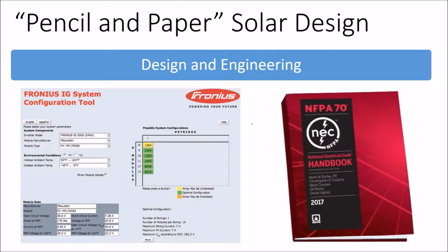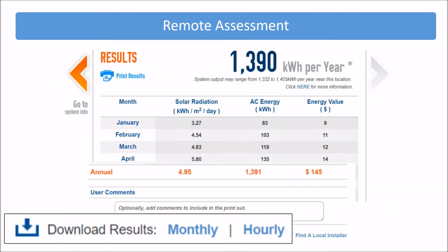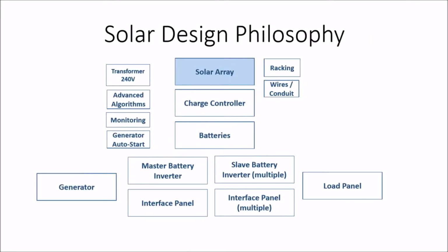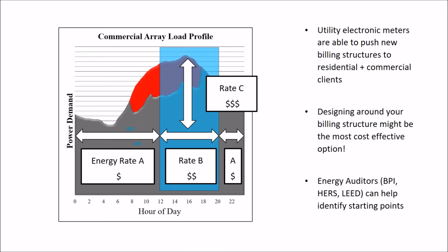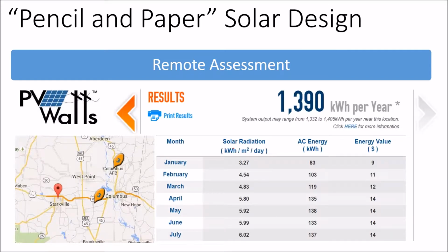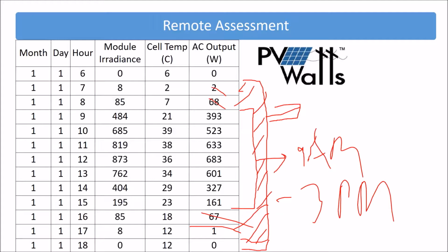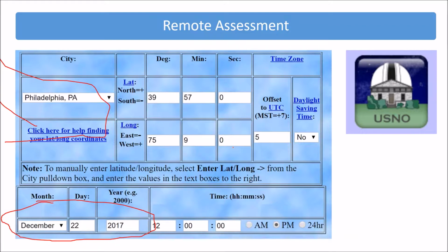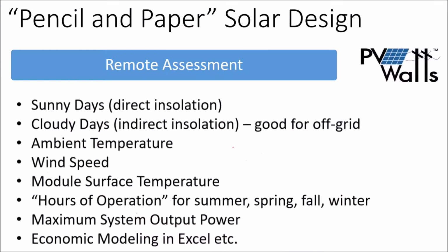So back to our program, where, after you can tile how many modules you use, what you do is you pull up Google Earth, you measure out your roof dimensions, you analyze the shade, you get your building height off the shadow, you get your tree height off the shadow, you compare the two, you pull open PV Watts, you get that hourly data, you find where your solar window is, you look at where those shadows are under a variety of extremes in combination with your sun angle azimuth chart.